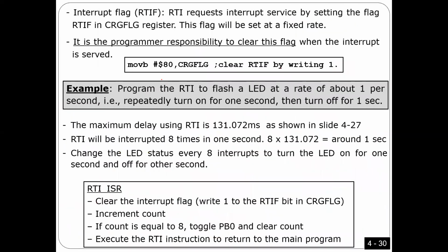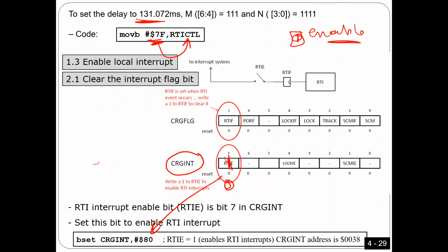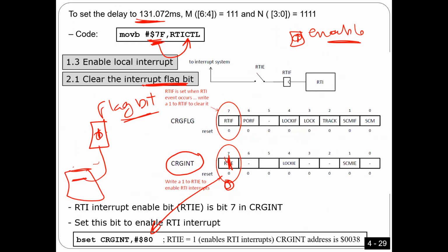Okay. Now the last thing I want to teach here in the configuration: I told you every interrupt source should have a flag bit, what we call an interrupt flag bit. The interrupt source is going to put 1 there, and in the interrupt subroutine you have to write an instruction to put 0 to clear it because I served it. So when I serve your request, I'm going to put 0 here. That's how it works, all right?